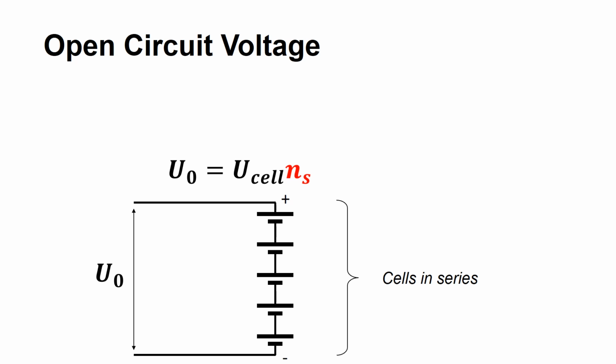But we also need to have a voltage high enough in order to be able to switch the electrical motor and form a proper PWM wave. PWM stands for pulse width modulation. If the voltage is too low, we will need to add another DC-DC boost converter to raise the DC link voltage, which then introduces additional losses and costs. A common voltage level today is 400 volts on the DC link.